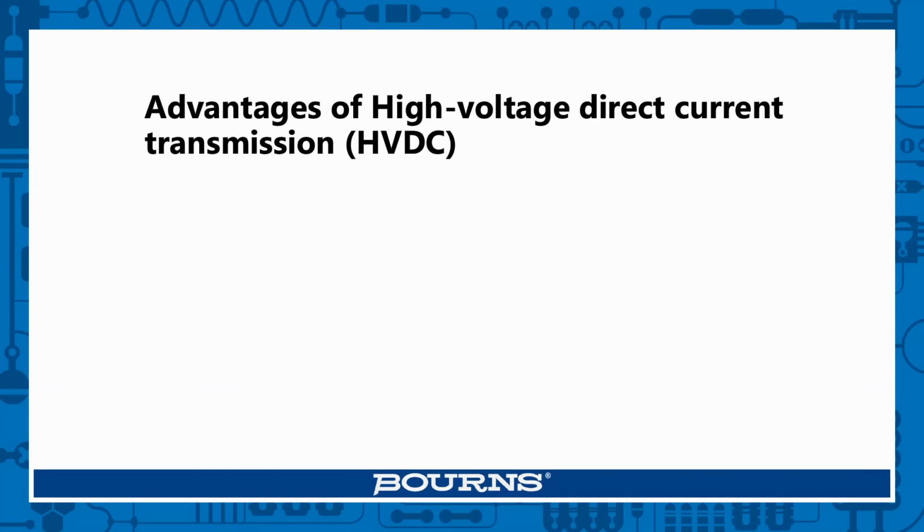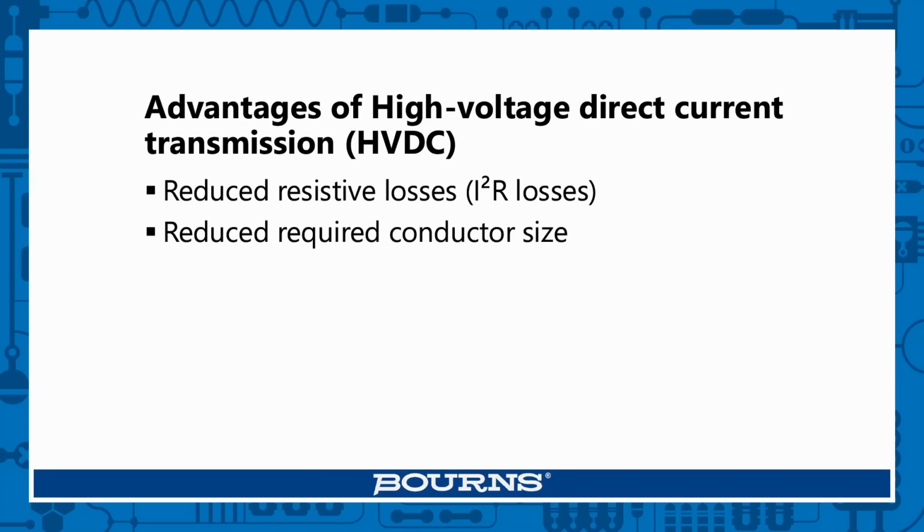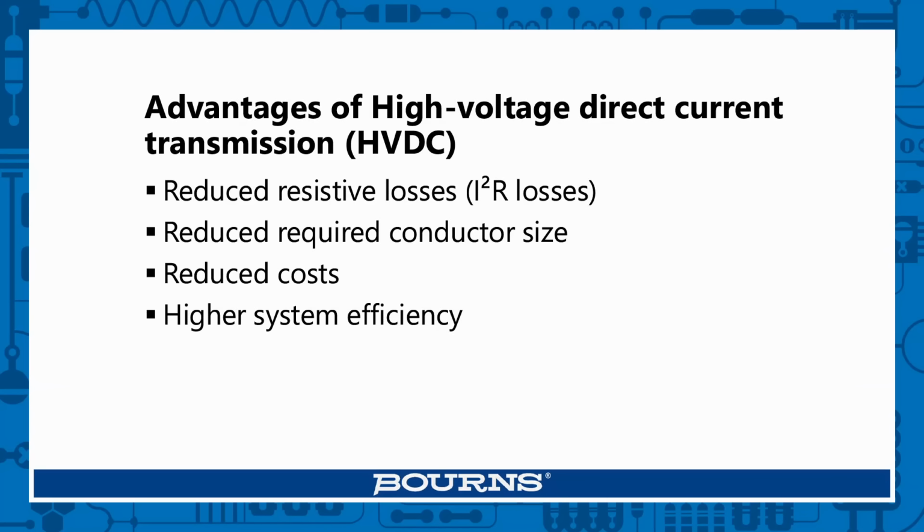So that means we're going to have higher working voltages. We see 800 volts more often now. We see solar inverters with solar cells producing outputs of over 1,000 volts, 1,500 volts. All of this means that the converters themselves, the actual switching devices, need to have higher working voltages.